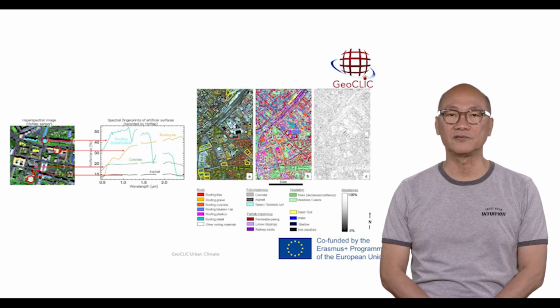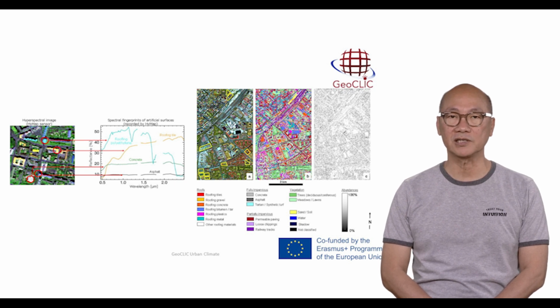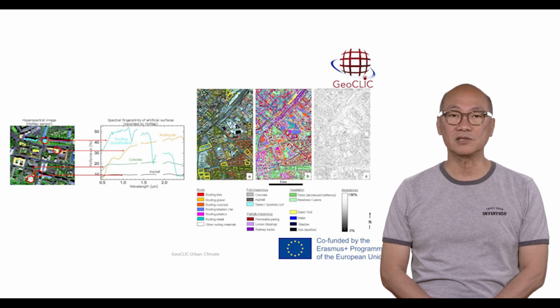This is an example of using hyperspectral remote sensing to define representative spectral signatures of urban materials. The first important category is roofs. Then, hyperspectral image can also be used to refine the characterization of impervious surfaces. The last figure to the right-hand side is the output of spectral unmixing method. It shows the estimation of pixel fraction of imperviousness, which is an important input for surface runoff model.